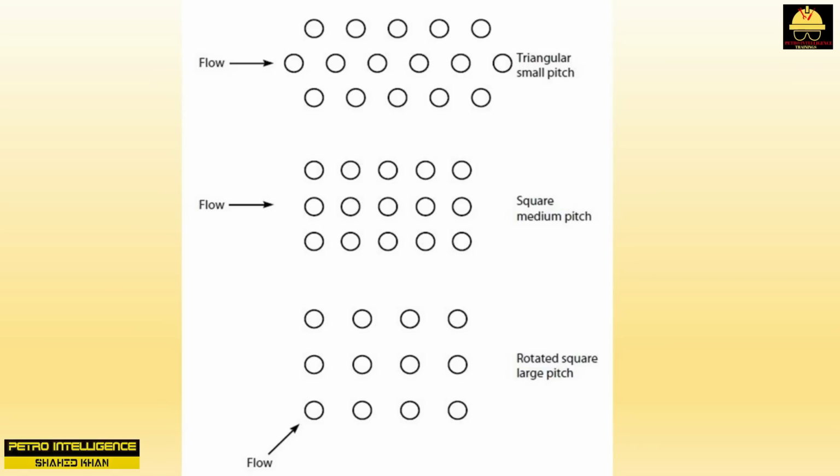The advantages of this tube pitch are: many tubes are squeezed into a small shell ID. The tube spacing promotes turbulence and hence good heat transfer. This all results in reduced capital cost. The disadvantage of this tube pitch is that, except for the outer few rows of tubes, the shell side cannot be cleaned by hydroblasting. Obviously, this sort of arrangement should never be used in a fouling service, unless the deposits can be chemically removed.